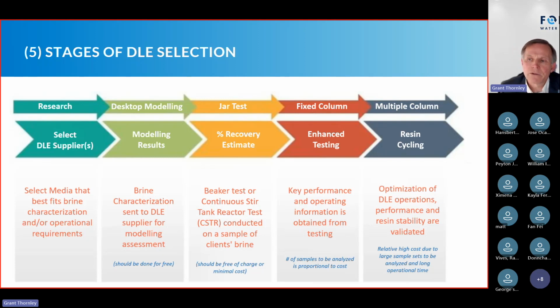As I said, microcontaminant loading on the DLE media is not going to be really noticeable at low volumes or low cycles. So as I increase that, if there is going to be a problem, I'm going to start seeing it at 30, 50, 60, 100 cycles. And if I do see that, that's great, you can address it. But if you didn't do these higher cycles and you did install the media, then the whole plant could come down in very short order.